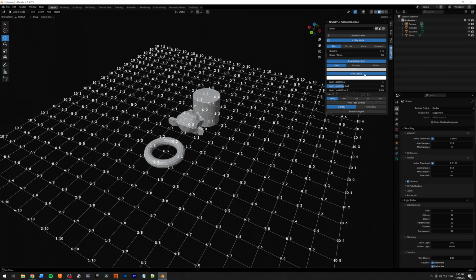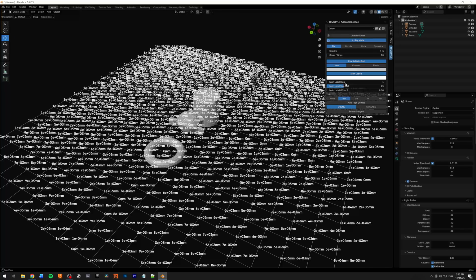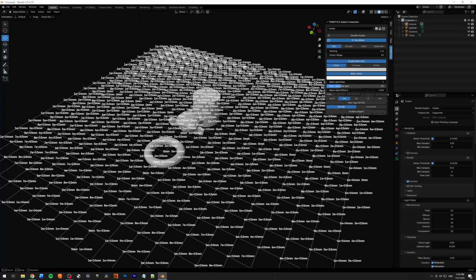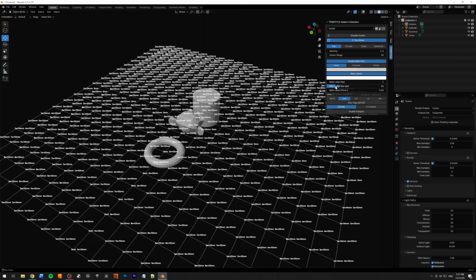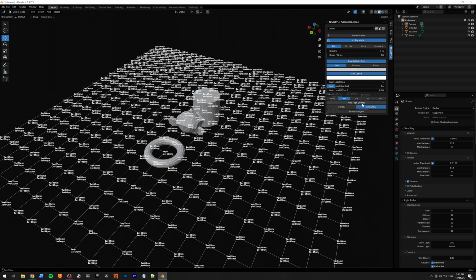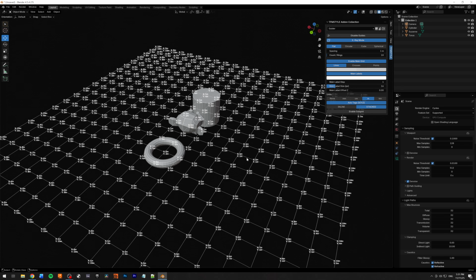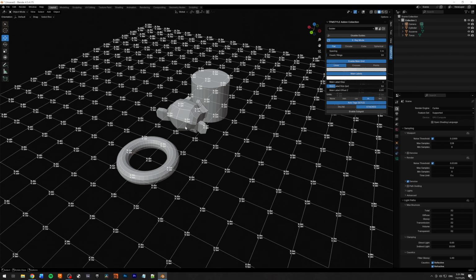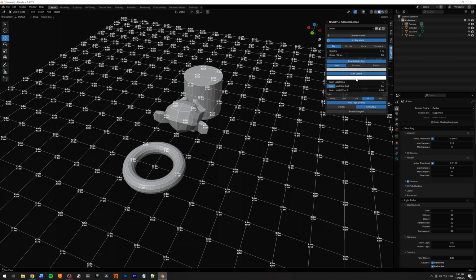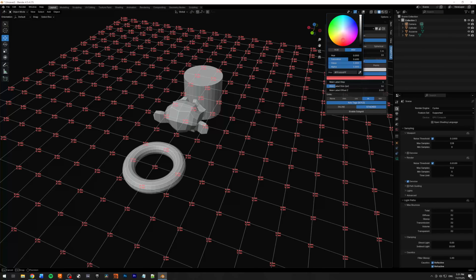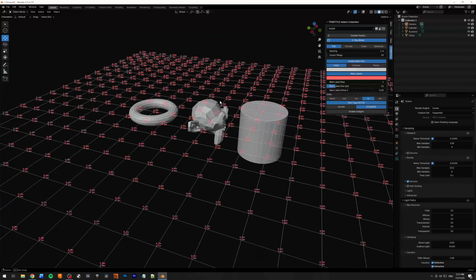And in this case, the label you can change. I'm going to turn down the label scale. I'm going to stack this, and I'm going to set this to meter. And I'm also going to enable the axis. So now you can really see each point, what position they are in. And you can change, of course, the label color, which is nice.